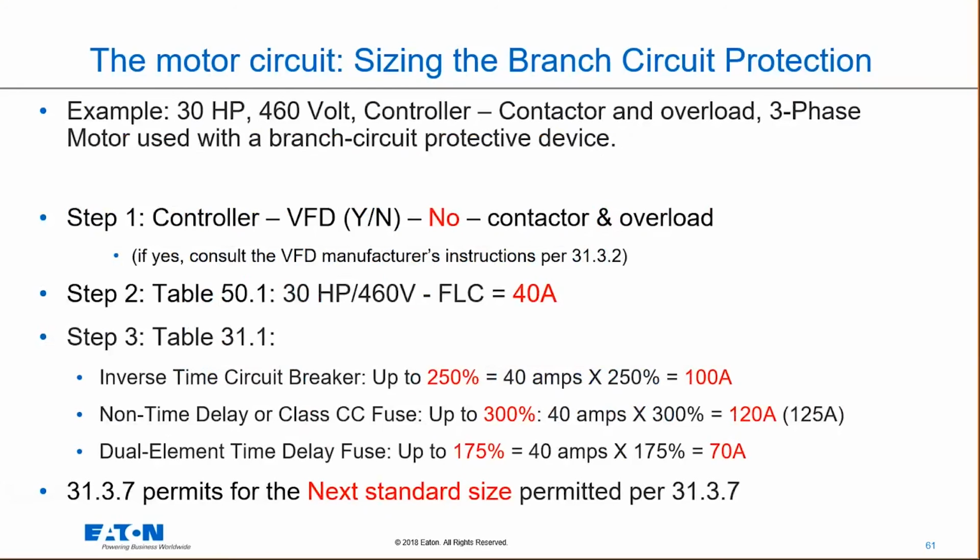In this particular case, it's no. We're going to have a contactor and overload. But if it is yes for some reason, and you are using a VFD, you want to look at the VFD manufacturer's instructions. Under 31.3.2, the individual manufacturer of that VFD will typically spell out what they want their overcurrent protective device to be. So be on the lookout for that. Take a look at your VFD manufacturer, see what they recommend, and use that.